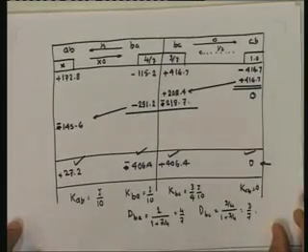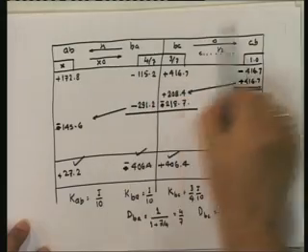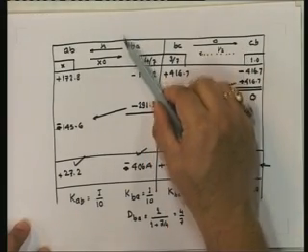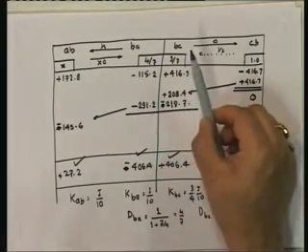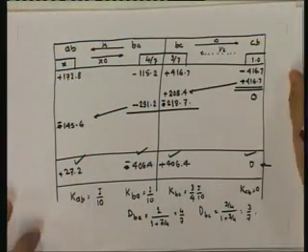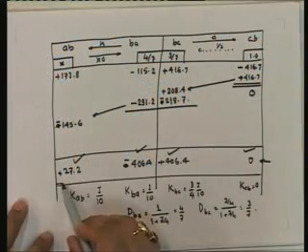There's only one iteration. Why is there only one iteration? Well, because since this is released, this is the only one clamped. As soon as we release it, okay, we've got balance here. That's it. There is nothing else. Theta CB can go any way it decides to. Okay? So that is the reason why, if you look at this, how this is spectacular. We had 9 steps to get to convergence, and by using the modified beam, we just did it in one iteration and reached the solution. Okay?